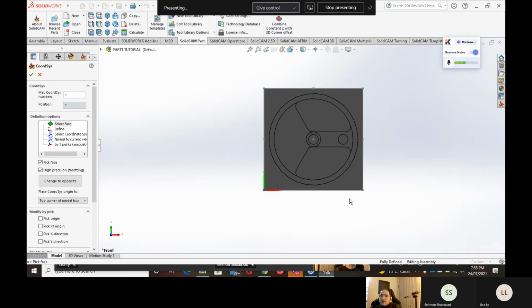If I'm going to work on a part like that on a CNC milling machine, on the table, if I would like to hold the part, I'm going to hold it using a vise. The vise has 2 sides. One of them is going to be fixed, the other one is going to slide. Try to remember that. We're always going to have the fixed part in this direction, while the slide jaw is going to be in